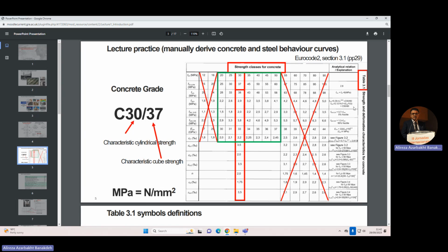And that's expensive. You don't use these two because they are not really structural concrete. You use them for pavement or for some infill walls which are not structural. They are not working for you as a structural element. They are very weak here. You will probably look for this green box here. This is the very basic concrete, and these are a little bit more advanced. So I just went for C30/37 here.